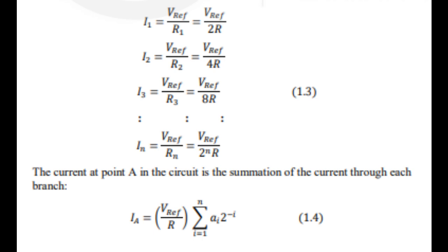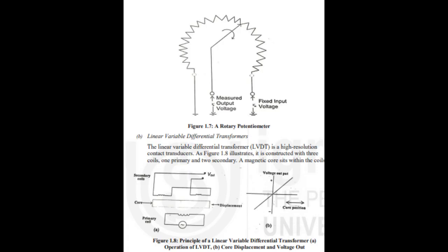The important properties discussed in this section are position, velocity, force or pressure, temperature. 1.6.1 Position transducers. Position transducers are widely used in servomotors, linear position tables, and other applications where precise position is important. In this section we will discuss 4 analog position transducers: potentiometers, linear variable differential transformers, floats and resolvers, and 2 digital position transducers, the optical encoder and ultrasonic range sensor.